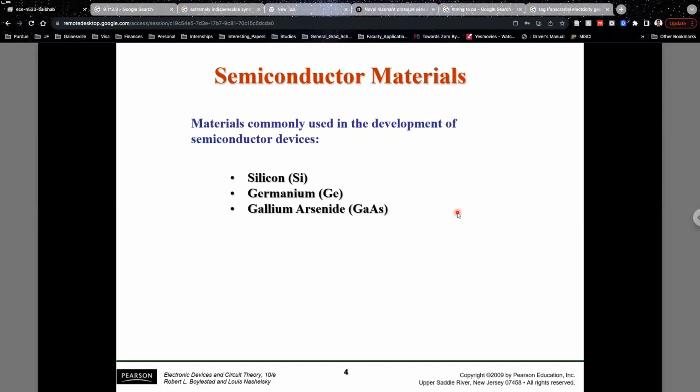So when you have these additional electrons or holes, there is a possibility that they will move from, let's say, one atom to another. There was an additional dangling bond over here. If you can make these additional dangling bonds move, you have a current flow. So the semiconductor becomes more like a conductor when you have more and more impurities like this. That's the reason why you create these p-type or n-type semiconductors from the pure semiconductors, which are silicon, germanium,